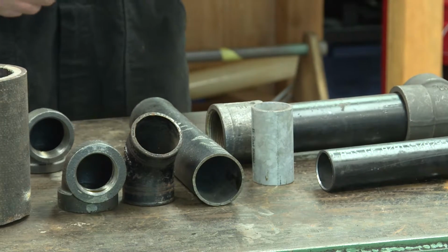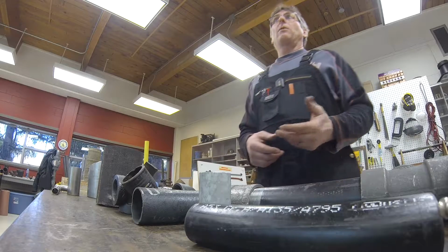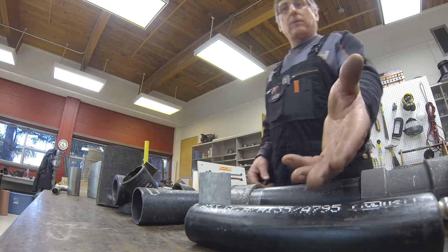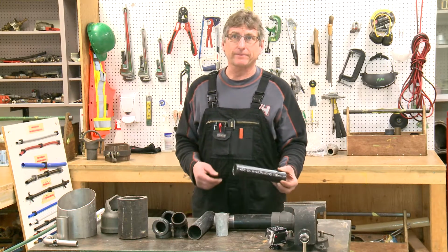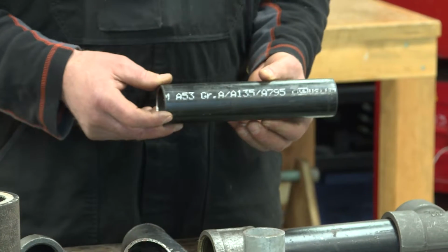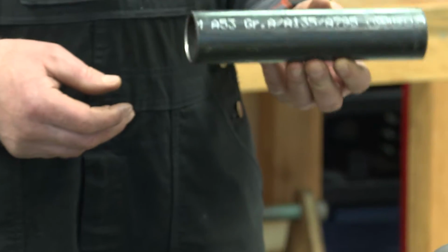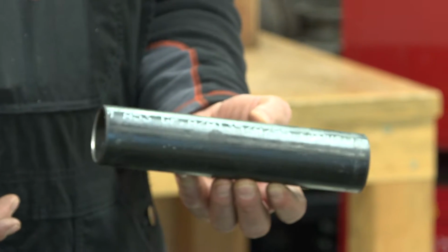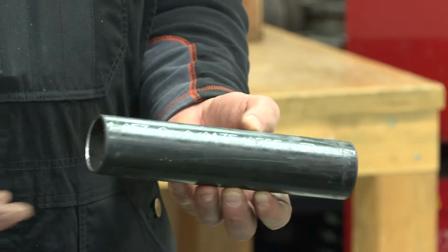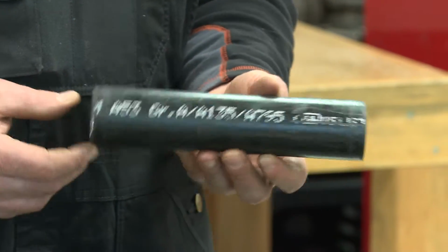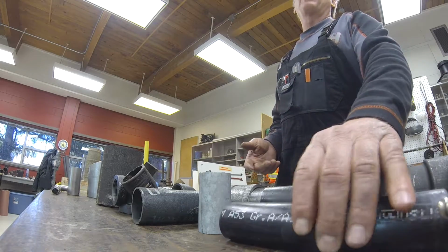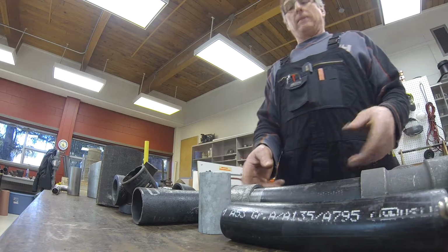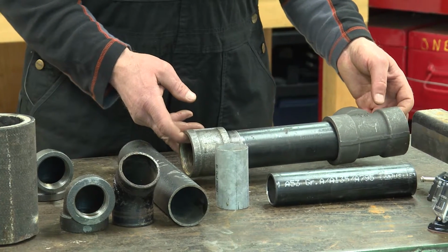What is an alloy? Well, starting with iron alloys, we have steel pipe, also known as iron pipe or carbon steel. It's available in either grades A or B. The grade that you require will be specified for your application, depending on such characteristics as tensile strength or ductility required for bending. There are many different methods for connecting steel pipe. As you can see, a couple are shown right here.